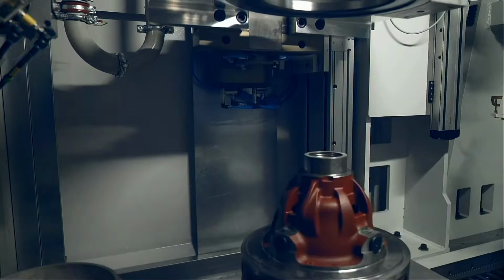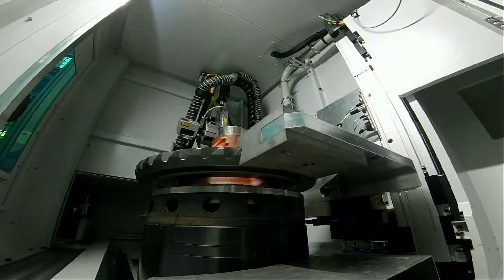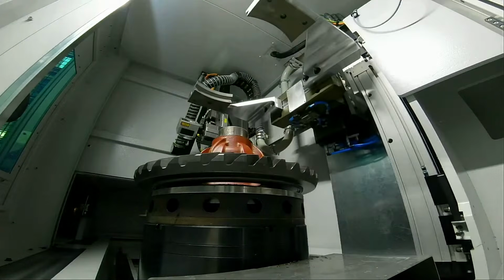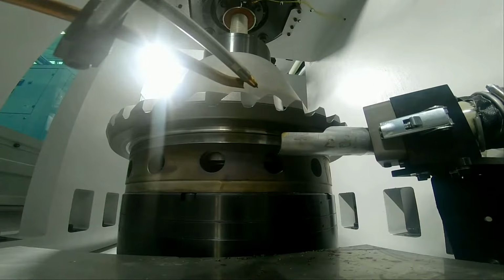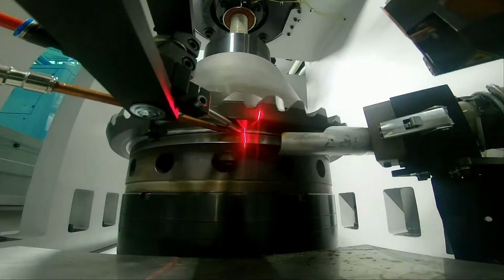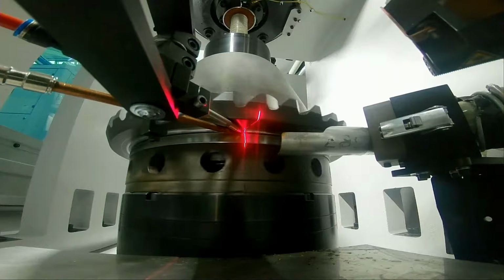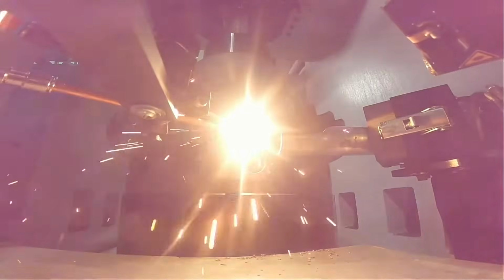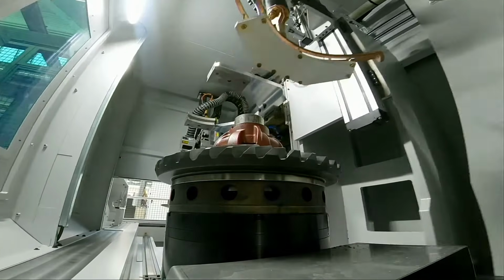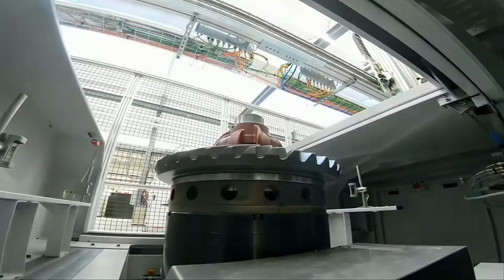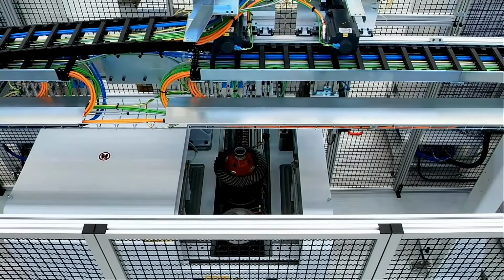The cast component will be moved underneath, and then we load the parts together in the right axis and position. Then again joining, and here we now see very nicely how the weld seam detection is working. So now we have scanned the weld seam, and then we start with the welding operation itself. Here shield gas is also included, as well as filler wire, plus a very closed fume extraction pipe to make sure that we are exhausting the whole fume during the welding operation itself.